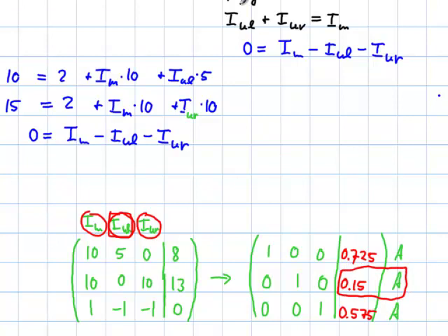And what we have to do for that, I think I'm running out of colors, so I go back to black, is that the voltage in the upper left equals the current that I just calculated, I on the upper left, times the 5.0 ohms that was given in the problem, and that equals, well, 0.75 volts, just like we saw earlier in the circuit simulator.